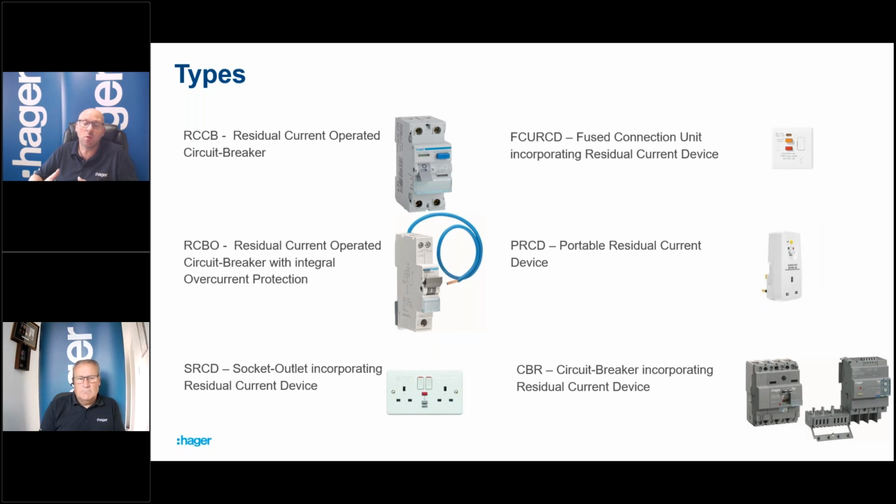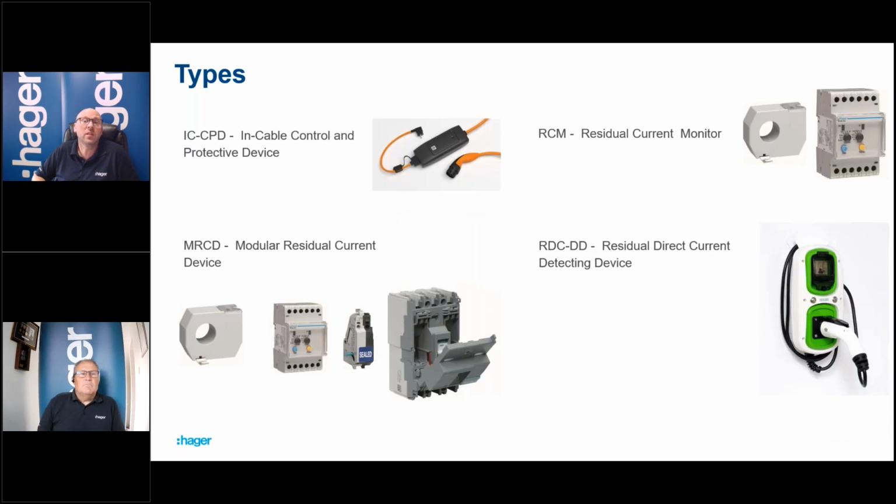Would it be to have an RCD that covered the whole circuit? Maybe it's just a part of the circuit. And that's where we see these different devices you can see on the screen there, from socket outlets to fused connections, RCBOs. We've got portable plug-in RCDs. So lots and lots of different devices use the same sort of terminology. And then we start to see them creeping into other places as well.